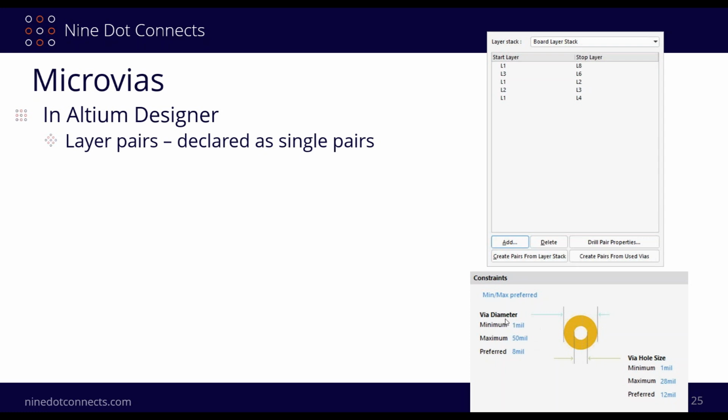Altium always defaults to 10 mils. So obviously you're going to have to drop this down to 1 mil or possibly less, depending on what the fabricator is going to allow you to get away with. By the way, the accuracy of Altium Designer, at least in the old coding, I don't know if they changed this with the new coding they did, but in the PCB editor, when I worked at Altium, you could get 6 places if you're using imperial, 3 places past the decimal if you're changing it over to metric. So just to be aware of that.